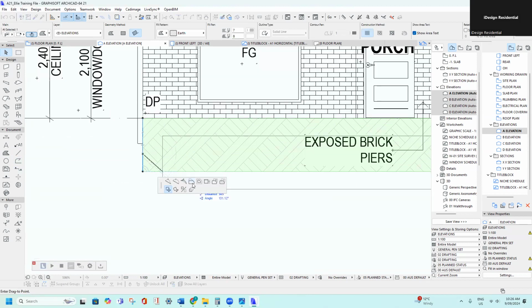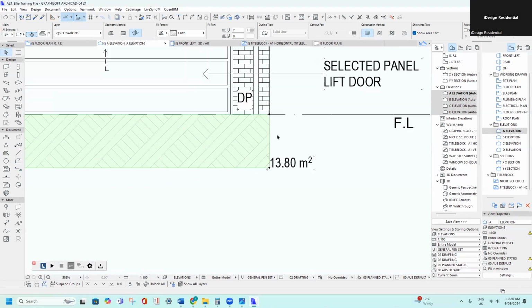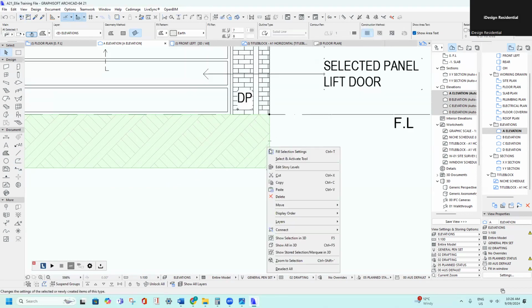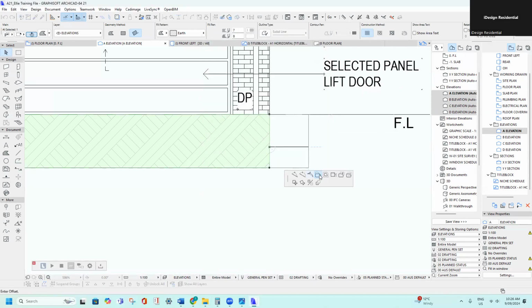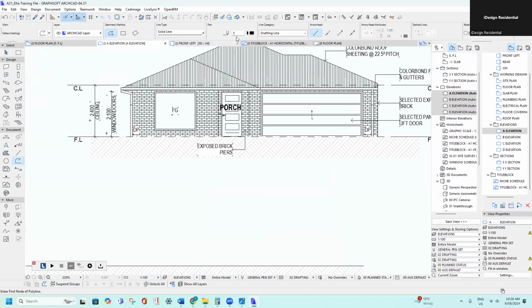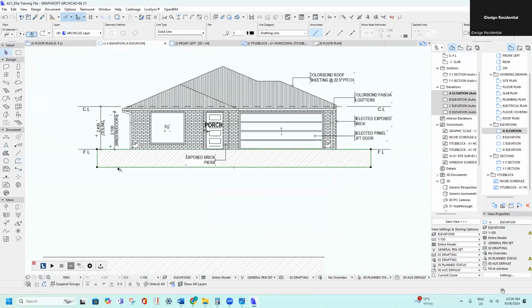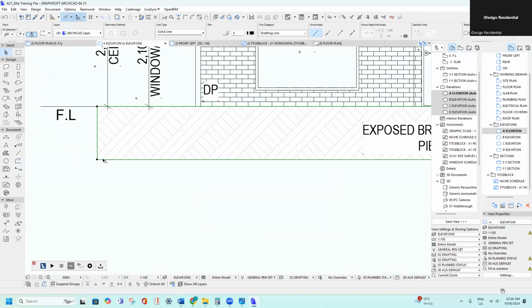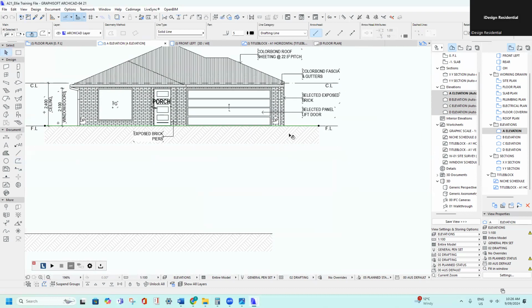If you click on the edge there, click that, bring it over 2 meters. Take that area off. Click the edge, get that option, bring it over 2 meters. So I draw the fill first, then you can draw the line at 5, hover over the edge, click. Then I press escape and I click it, highlight it, and then press control and just trim off those. That's another way you can do it, which I found is a little bit quicker.